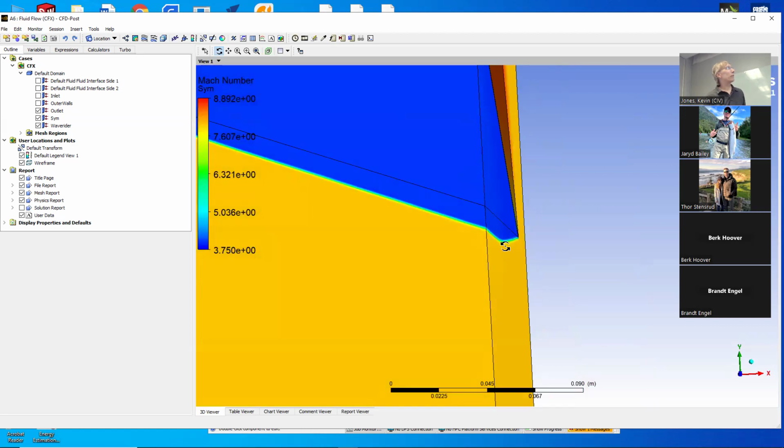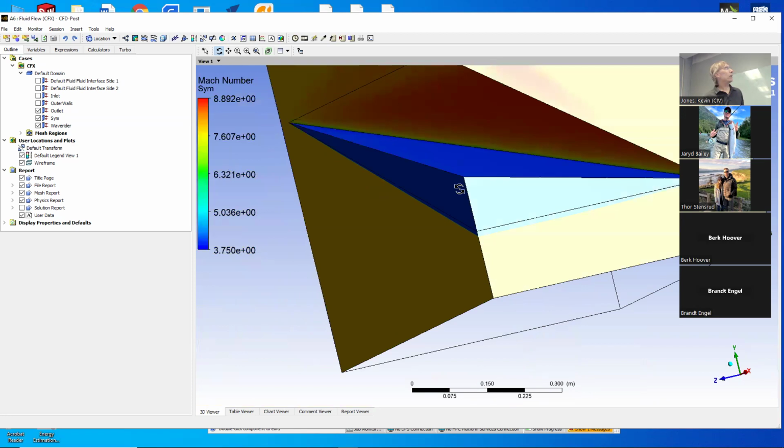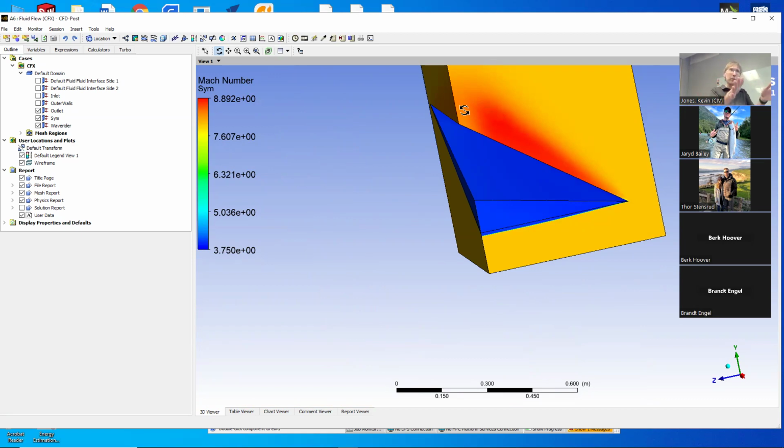See from the back there, this is the outlet. And now on the upper surface, we now get an expansion fan because it's now expanding. And there's actually some weirdness at the symmetry plane because I guess from the left and the right, you get 2 expansion fans and they somehow interact with each other. And so you get some dodgy stuff at the symmetry plane that's different.